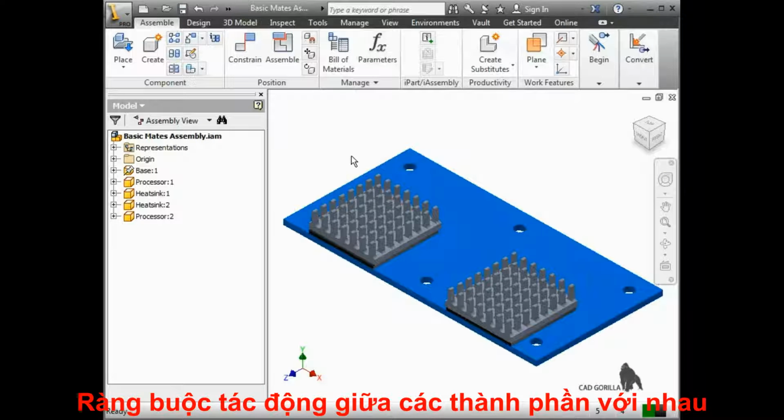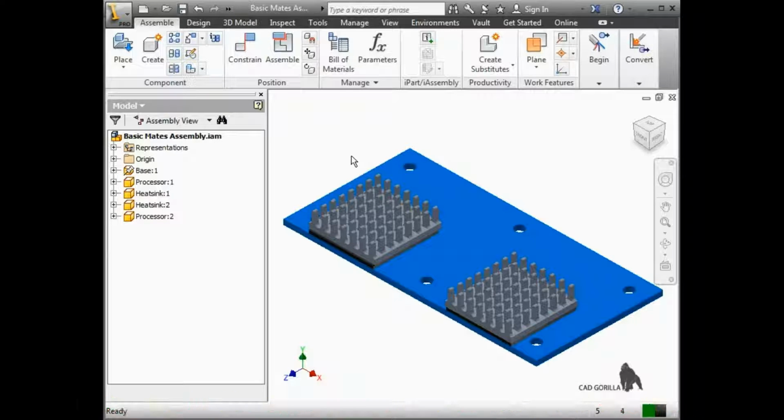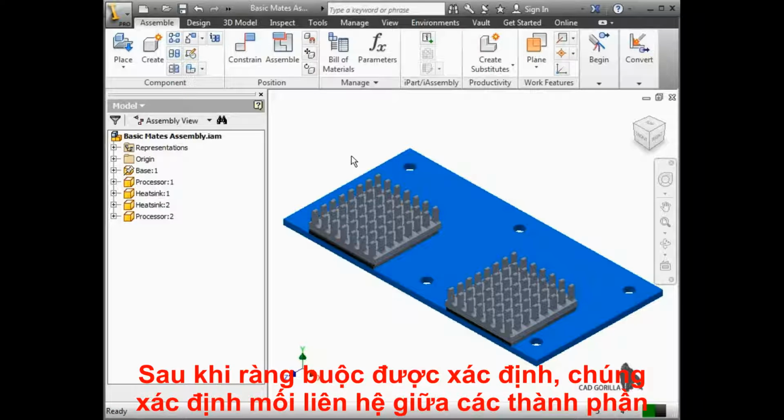Constraints are created between entities. In fact, they exist specifically to relate one entity to another in an assembly. After constraints are defined, some of the constrained entities can disappear for a variety of reasons, resulting in broken constraints. For instance, this can happen when a component's geometry changes, eliminating a constrained face or edge, or when a workplane is accidentally deleted or suppressed.